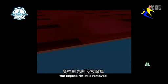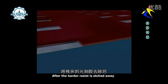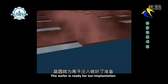When developed, the exposed resist is removed. The exposed silicon dioxide, where the N-wells will be created, is then etched. After the hardened resist is etched away, the wafer is ready for ion implantation.